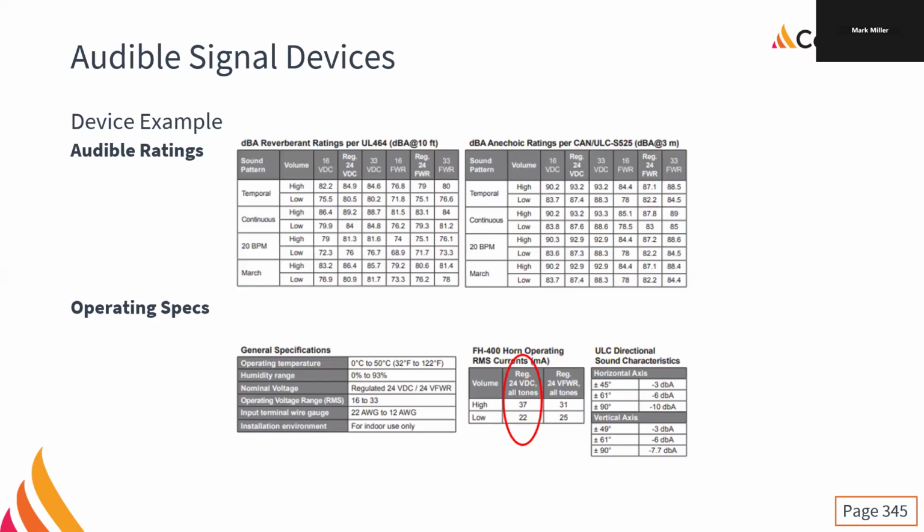No, the panels are actually not supplied by the batteries constantly. There was a time that they were, but it just caused a lot of trouble with the batteries. The power supply provides a clean 24 volt DC to the panel, and it supplies a clean 24 volt DC for charging.